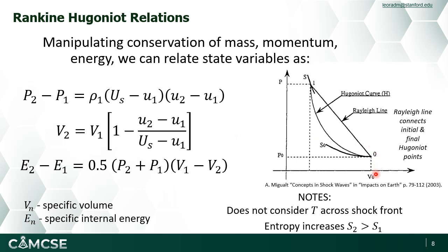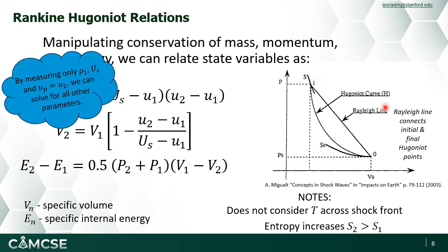Similarly, it's important to understand that a shock wave also obeys the second law of thermodynamics. Entropy must increase in the universe. And so indeed, what we find is when we look at these isentropes, the isentropes become higher and the entropy states increase as you go, validating for us that, of course, it makes sense that we now have a higher entropy in this much more compressed state.